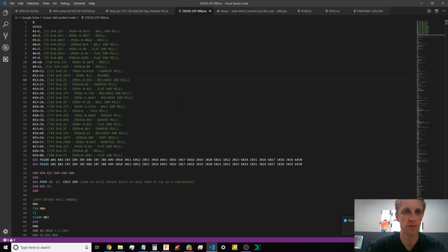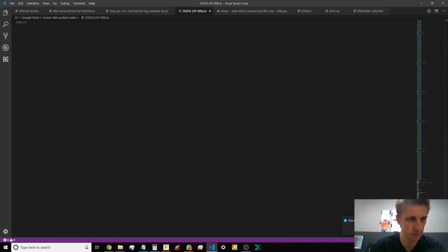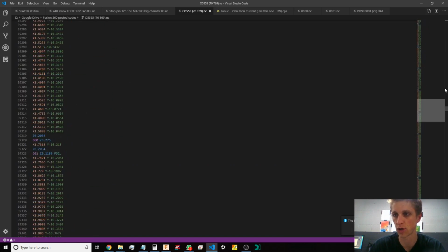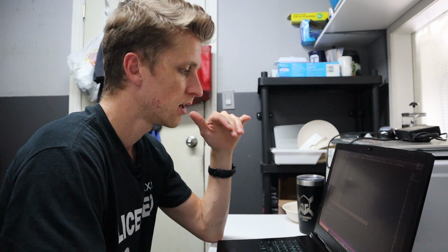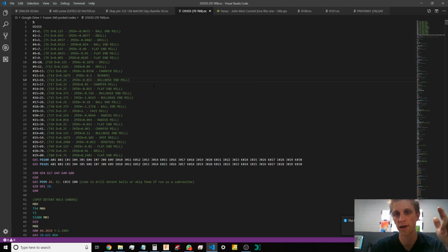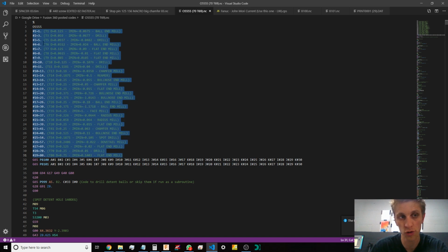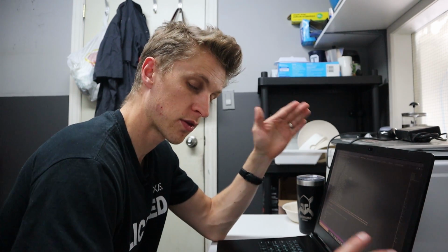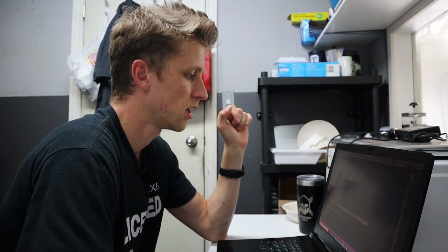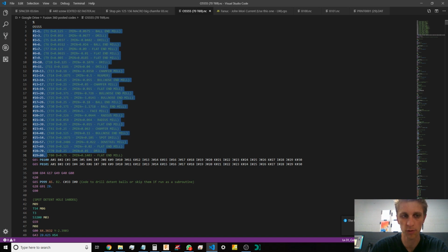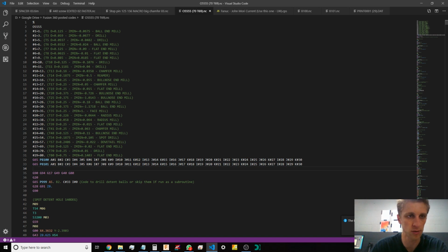This is the beginning of my Norseman fixture code. We have 140,000 lines of code. This does everything: handles, blades, clips, everything. I have modified my Fanuc post-processor from Fusion 360 to automatically output your O0555, and then automatically output the tool data, assigning each tool number to variables 1 to 30. Variables 1 to 30 are those temporary hidden ones. The second you leave that subroutine, they disappear. All I needed was to write to those variables and then read them on the very next line, and it'll tell me if it's good.